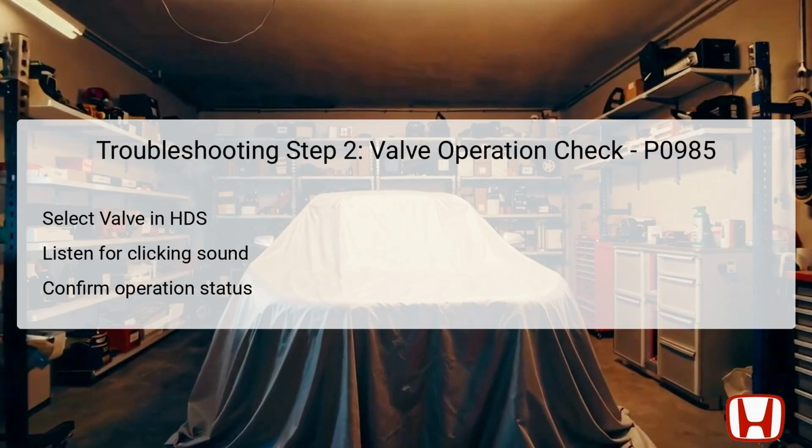If a clicking sound is heard, it confirms that the shift solenoid is operational, suggesting that the electronic command from the PCM to the valve is effective. In this case, progress to the next step in the troubleshooting process. On the other hand, if no clicking sound is detected, it suggests an issue with the solenoid's operation, requiring further investigation into the solenoid or its wiring before proceeding.